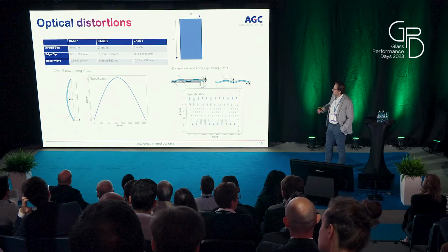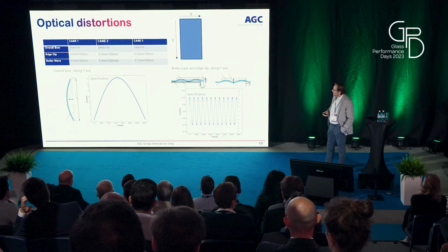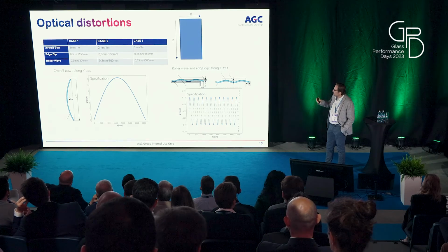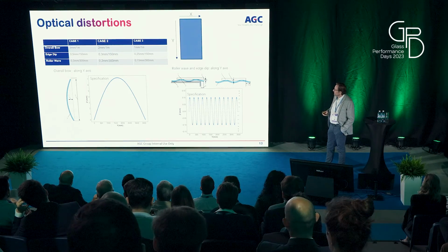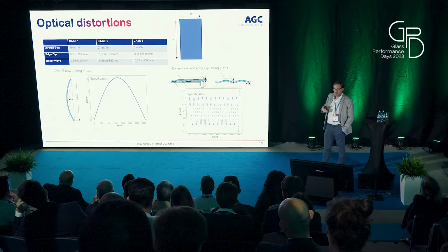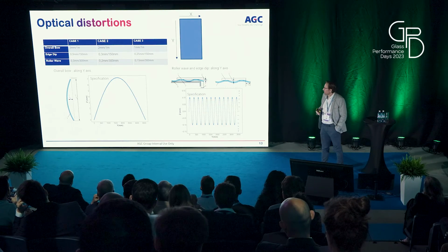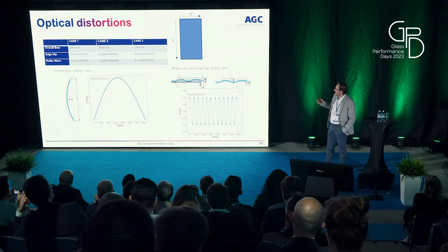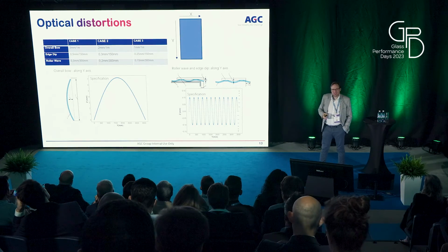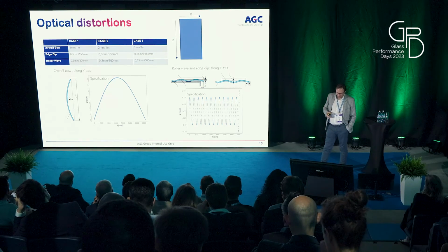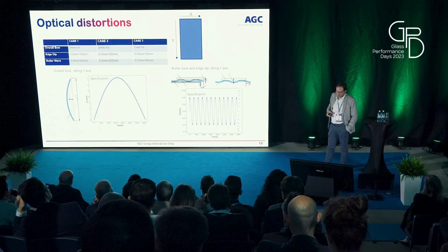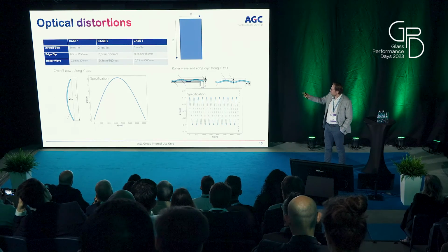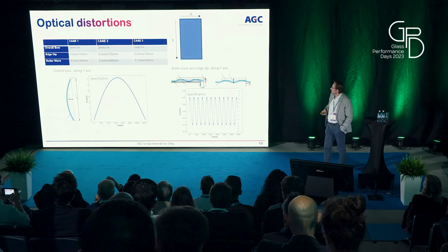We have, as you can perhaps remember back to the product standard of tempered glass, the overall bow of 3 mm per meter, and roller wave distortion of 0.3 mm per 300 mm. This is a standard tolerance. So with that, you get a really high distorted pane. You will see later. Then we have case 2, which is an optimized one, and a really good one is case 3 with 0.15 millimeters, focusing on the roller wave distortion over 300 millimeters.